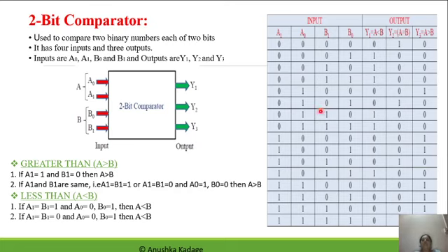With this rule the MSB of B is 1, that's why here B will be greater as compared to A, even though the A0 value is 1. So A less than B is set to 1.